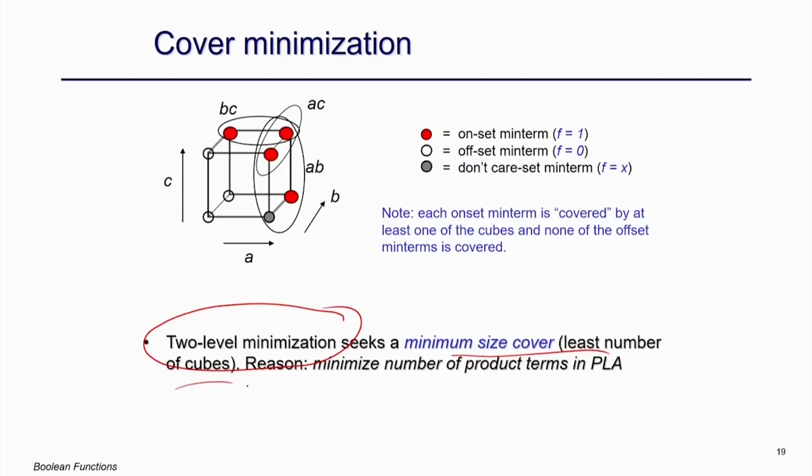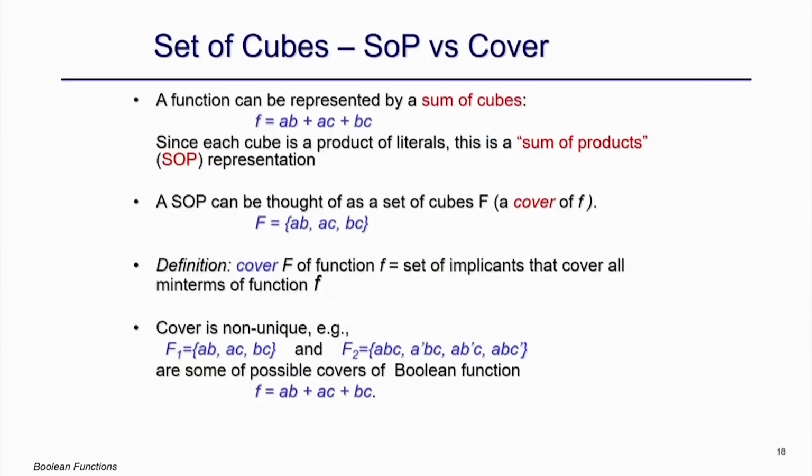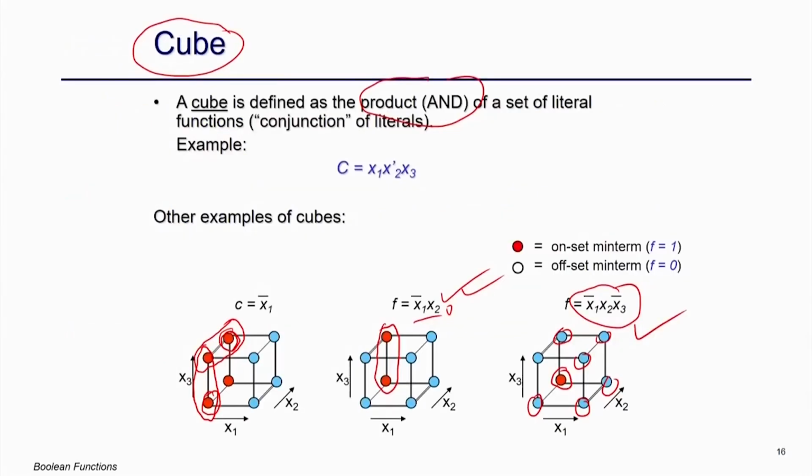So, that is the number of cubes which is covering all the product terms, right. That is what is called cover minimization. And why this is important, you understand that suppose I have these 4 values, whatever I just told you. So these 4 values is nothing but, if you write, my f is this, right.